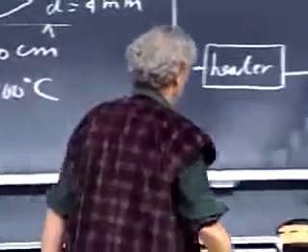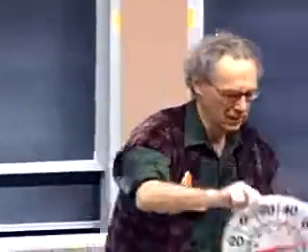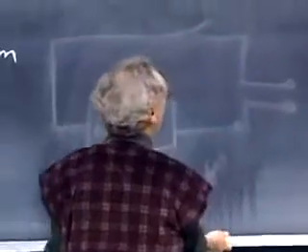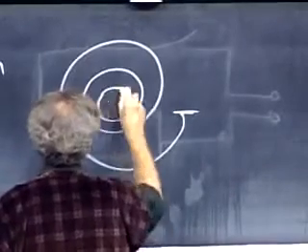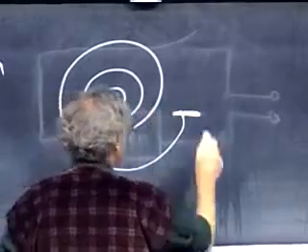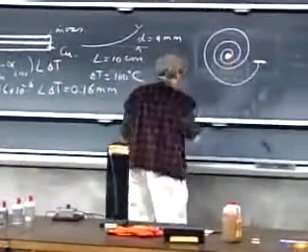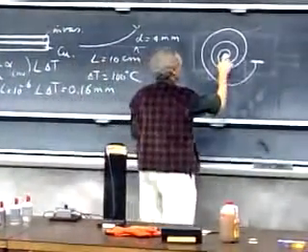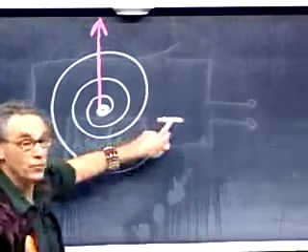Bimetals can be used as thermometers. In fact, the one that you see right here is driven exclusively by a bimetal. If you look in the back of this thermometer, and I will show that to you shortly because I broke one open for you, then it looks like this. There's a coil. This end of the coil is attached to the plastic casing. And here is the red hand. It's a pivot here. It's a red hand. So this is fixed. This cannot move.